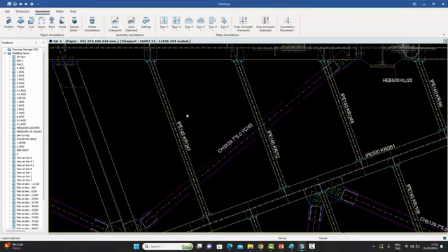And how do you use it? This one already has the existing annotation. So I'm just going to select this frame, and I'm going to say annotate the selected profiles. And now it has annotated it with the new one. This new one was basically what I just showed you. It's custom based. You probably made a bracket, then you wrote a P, and then you put this dividing sign, then the number, and then the bracket again, and the second line material.